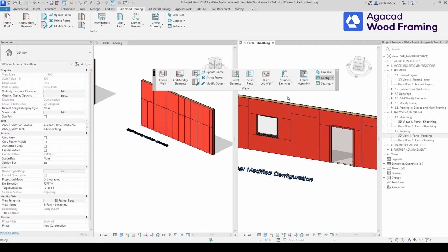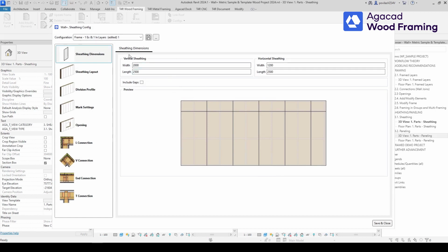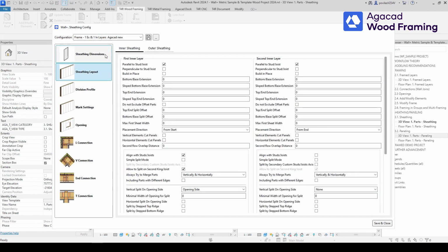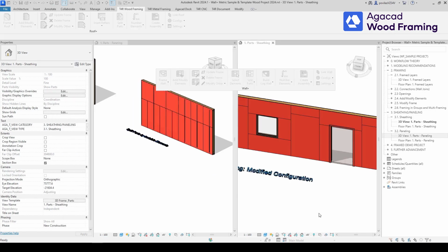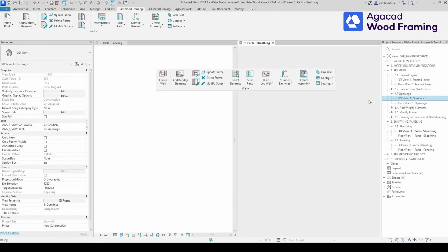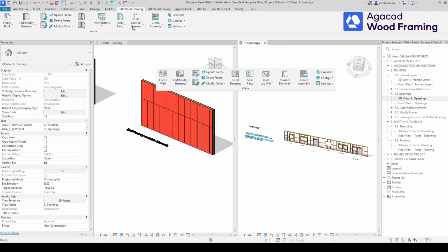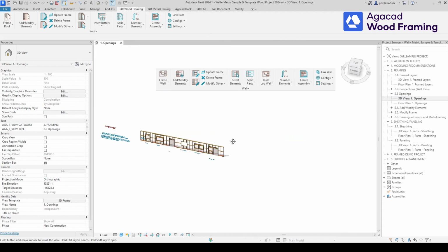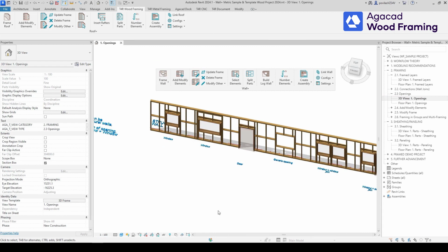If I now go into sheeting configurations, I will see that configuration sitting in there, which is quite a useful thing when, for example, you don't receive the configuration or you don't have the configuration, but you want to create a configuration from a given sheeting layout. So that's quite useful. Okay, so these were the hiding of unused tabs upgrade to sheeting and paneling.